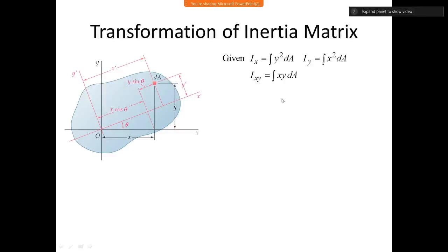So when I say inertia, it means the inertia matrix, and if we just talk about a simple 2D case here, the coefficients of this inertia matrix will be Ix, Iy and Ixy, whose definitions are given as follows in integral form. Now it may be possible that I want to switch the measurement axis, I want to rotate the axis of rotation.